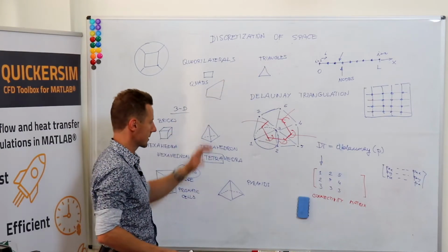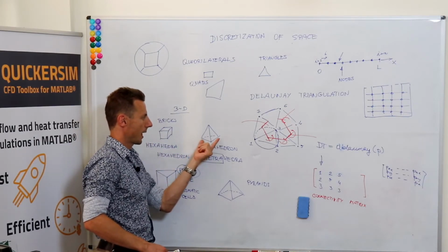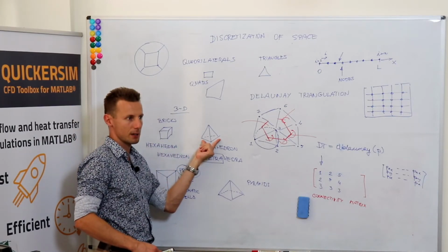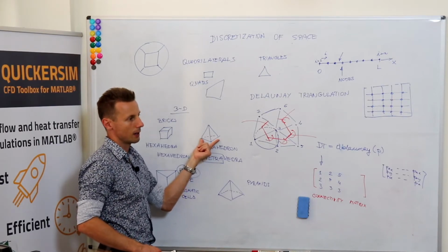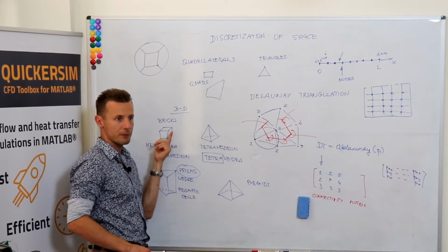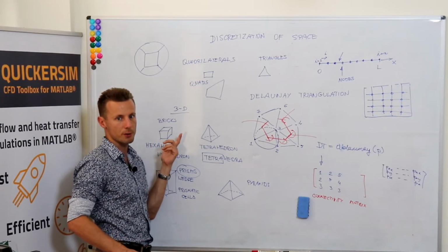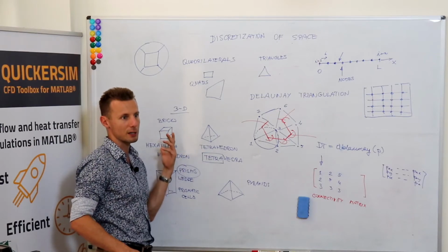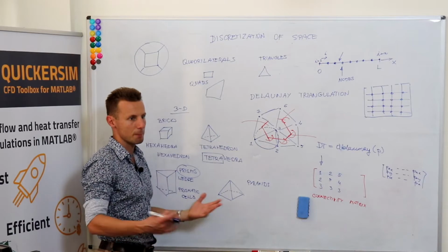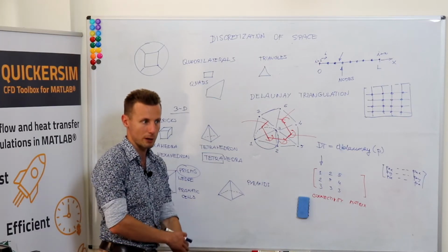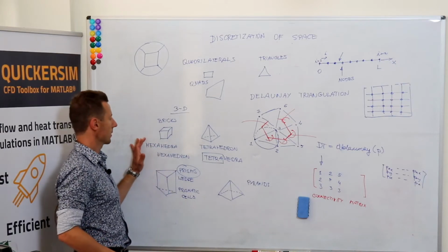Triangular meshes, yes. In 3D, it's important to say you can always subdivide space into tetrahedra. Again, the same problem with bricks. If you generate structured meshes, you can write algorithms for some basic shapes. This will work fine, and it's pretty convenient.